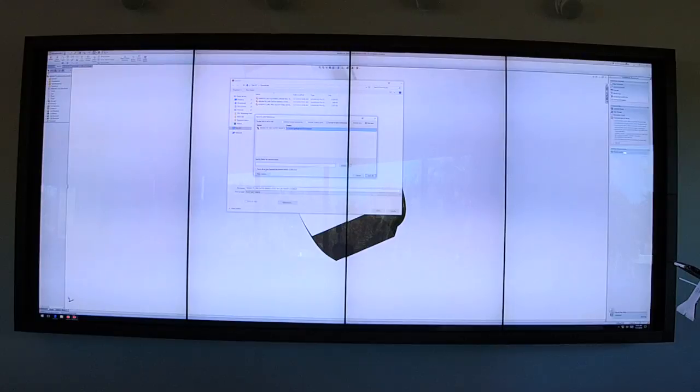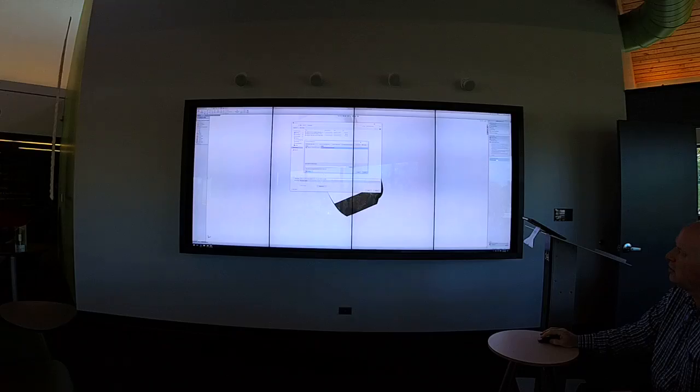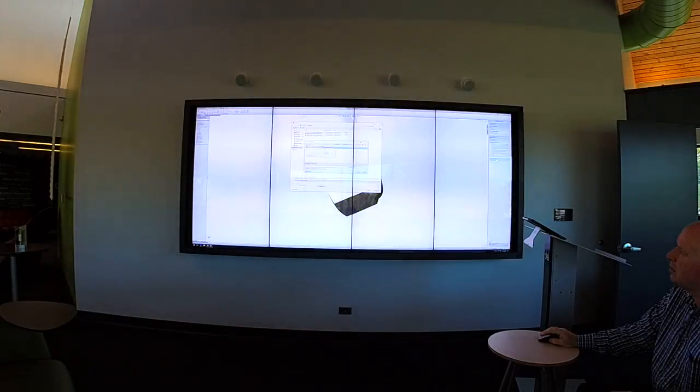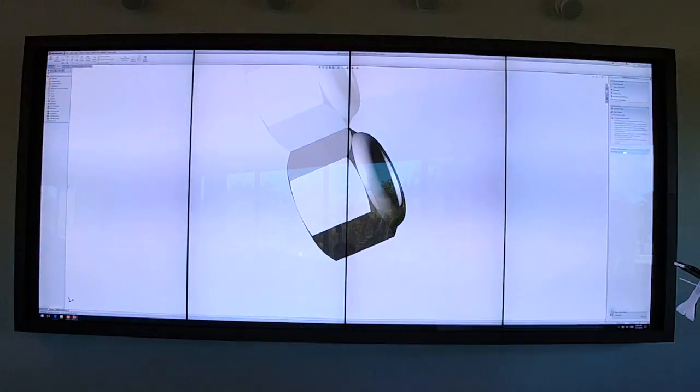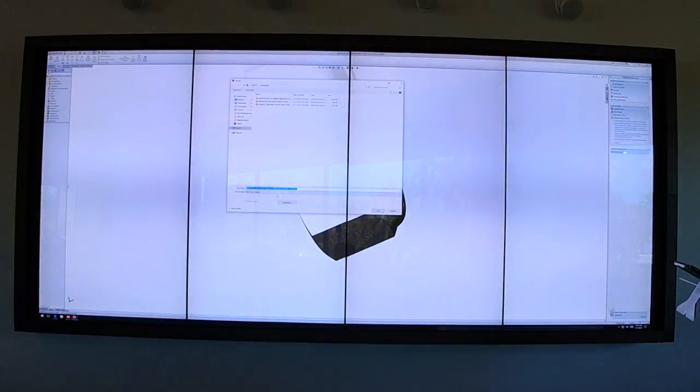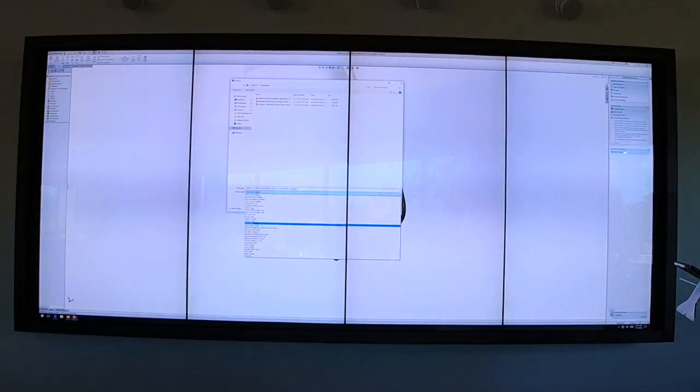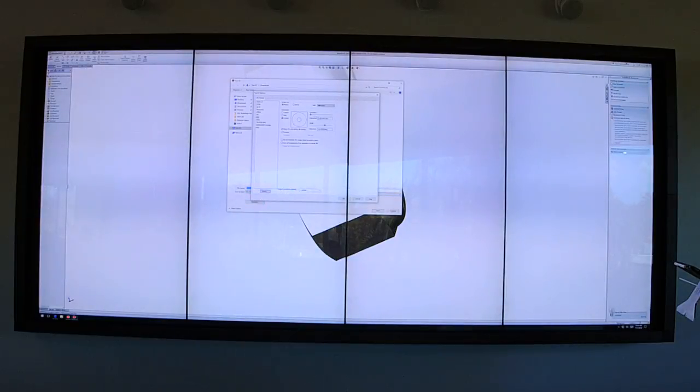So what you're able to do in your options, when we create an STL file again, is push this deviation up so the tolerance is higher. And what that does is create more faces, so it prints smoother. So the more faces you've got, the smoother it's going to be.